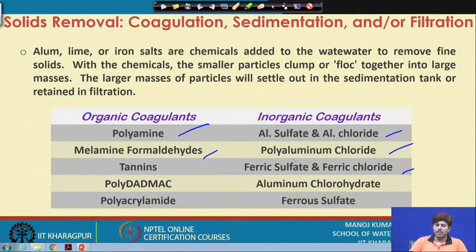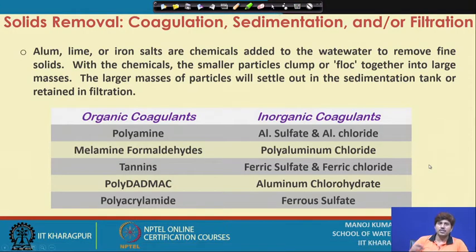So, particularly the salts of iron and alum that way. Okay. So, these are the methods to remove. The process is simple, just add coagulant, make a rapid mix, as we do in conventional water treatment systems. In a rapid mix we add a little coagulant and then allow it to settle for some time or pass it through a filter.